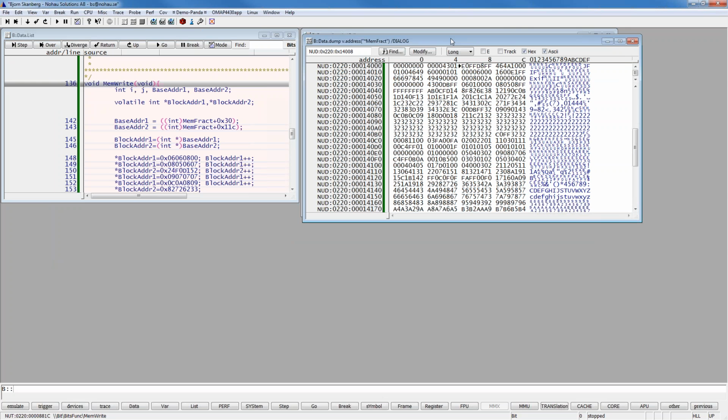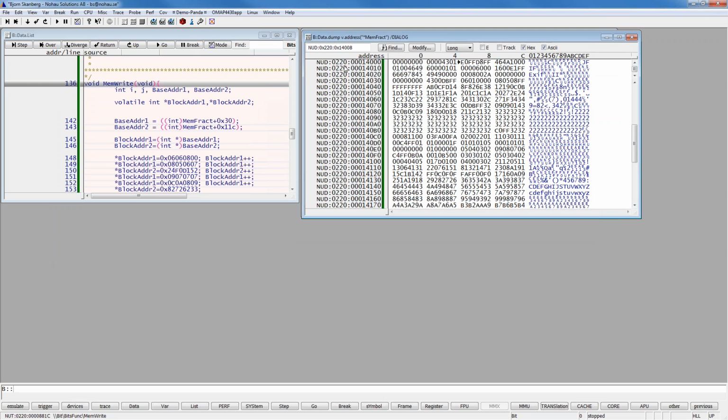which we have here. As you can all see, we're now in the space ID 220. So these are the virtual addresses because Linux is using the MMU. So it is translating physical addresses via the MMU to virtual addresses. So this is not the actual address of where this code is residing on my target.